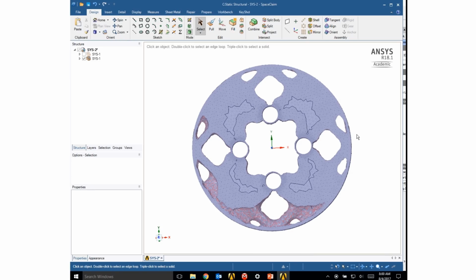So now this geometry here isn't very mesh friendly. It would be difficult to get a very good mesh to fit this. It also wouldn't be very easy to manufacture. So what I typically do now is delete all of the lines and redo the geometry with ANSYS Workbench.